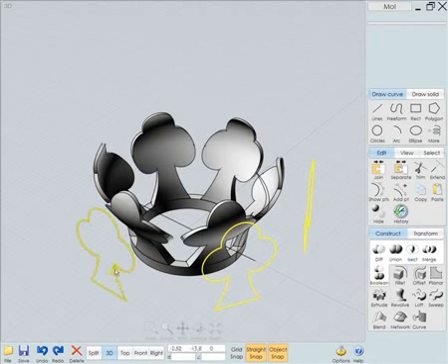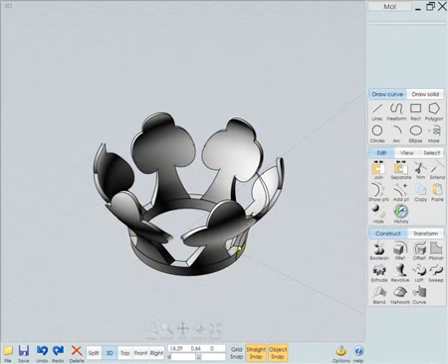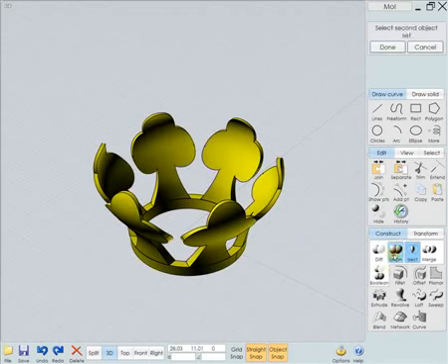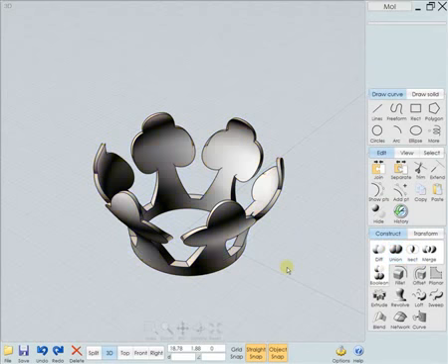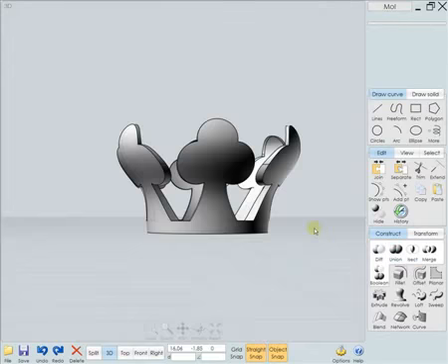Basically we modeled this shape and kept only the parts that intersect the inside of this with what was already there. We can now just delete all these curves that we used for constructing this. Now let's select everything and use Boolean union to fuse it all together into one single piece. And there you have it, one